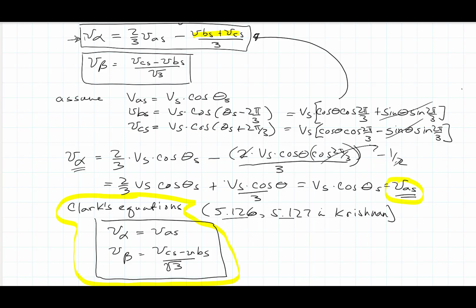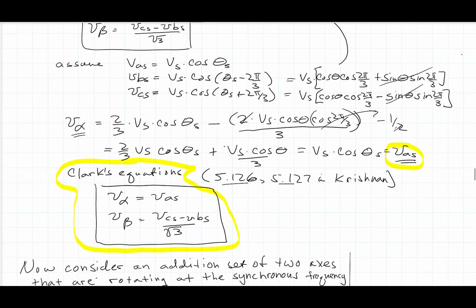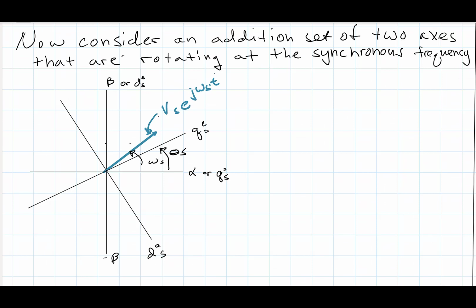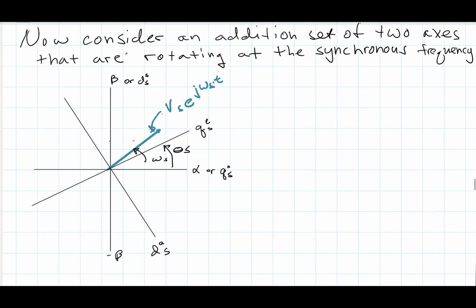Well, if you go into the drives industry, you probably hear this equation mentioned a lot, and now you know where it came from. I want to go a little bit further and consider the addition of two axes that are now rotating at the synchronous frequency. So I'm going to introduce a stator Q axis in the synchronous frame that's basically rotating.